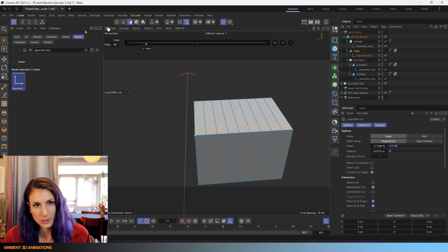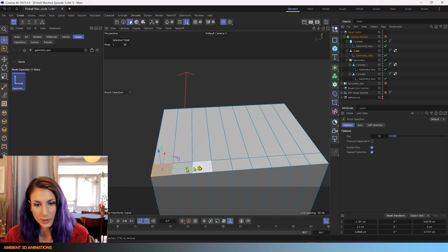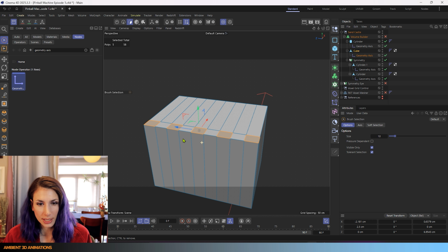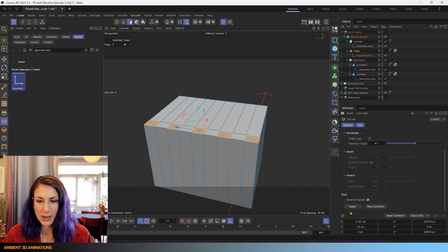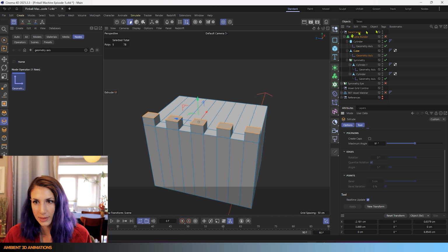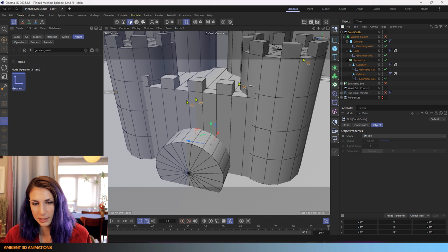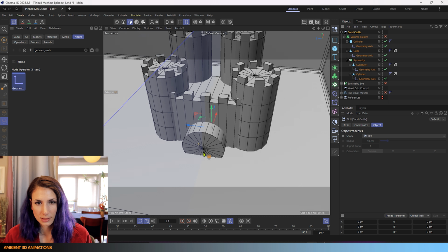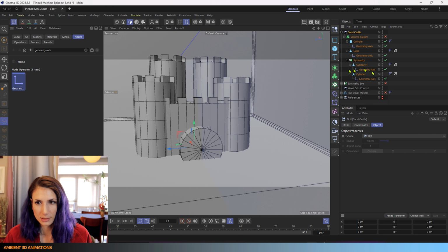And we're good. So everything is fixable, and it's easier to fix if you know the tools. So I do have YouTube videos covering all these tools we're using right now. If you'd like to give them a try, I'm going to click on those again, use MT. And if I'd like to extrude this the same amount as before, it's saved that amount, and I can just hit apply and I'll do it again. So now we're good. I'm going to unsolo this and click away so that it moves back into place. And you can see we have this nice little castle here.